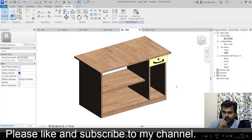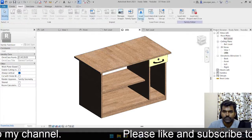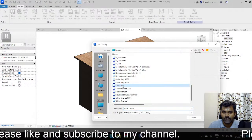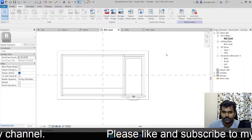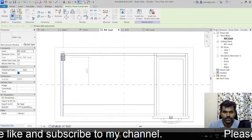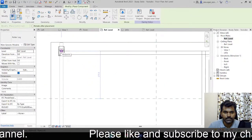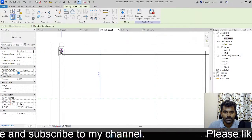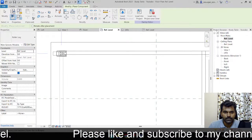What do we need now? We have to add 4 rollers. Let's do that. Go to load family, roller leg, open. Now go to reference level, create component. Okay, just place it in the center here. Oh, we can change it anytime. Okay, I'm just going to add it just here.